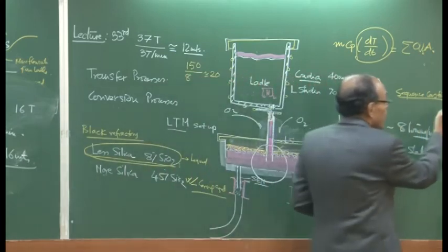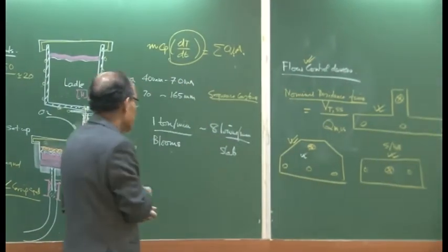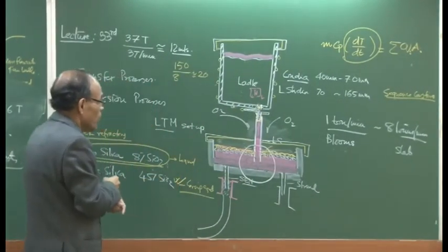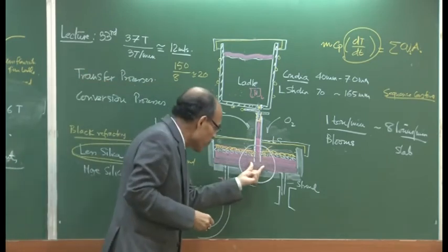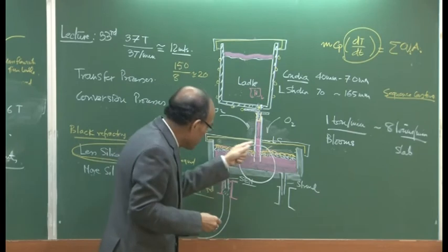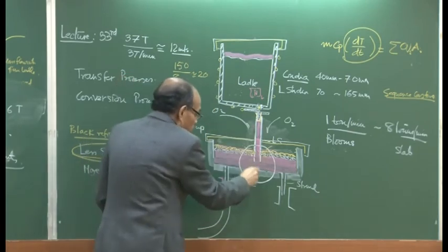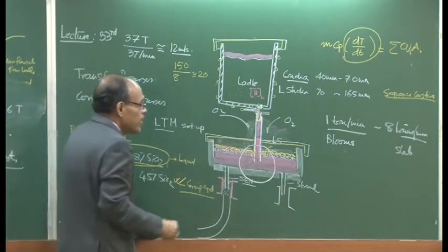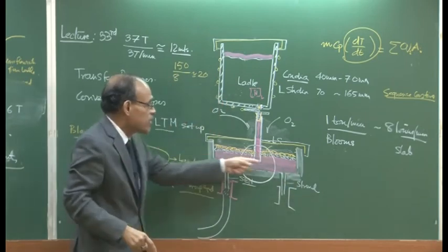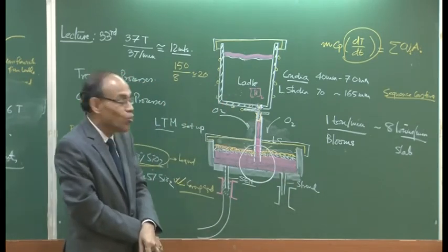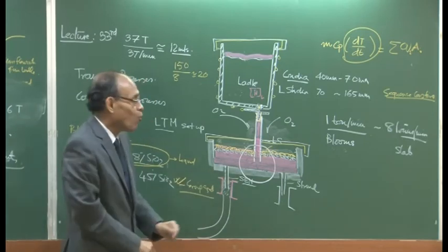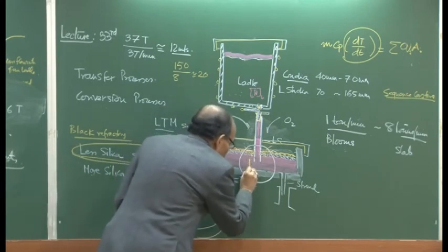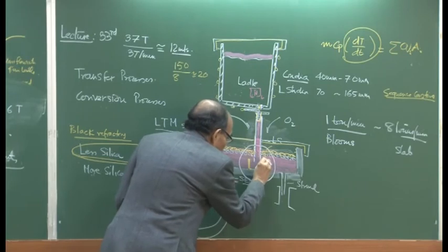So it is important for us to exploit this scenario, that the tundish spends some amount of time and we create a quiescent kind of flow scenario. That is why, because we have a very large turbulence available in this particular region because of the high flow rate of molten steel. So there could be quite a bit of slag metal mixing here also, okay? And that is why in a bare tundish, which means the tundish contains no flow control devices or flow modifiers, where molten metal will really be poured in, we will invariably have what is known as a pouring box or a turbo stop immediately below.